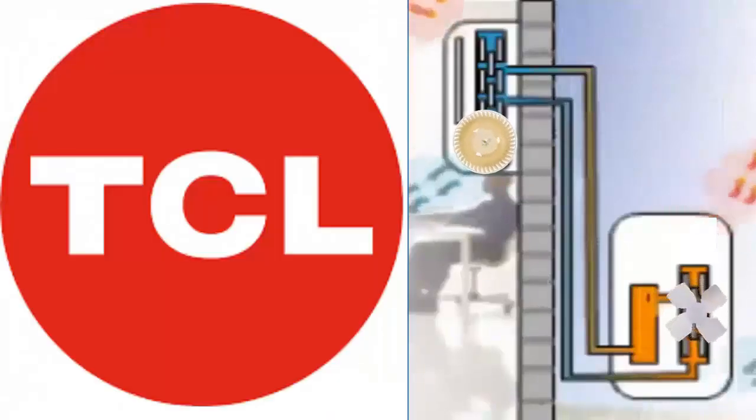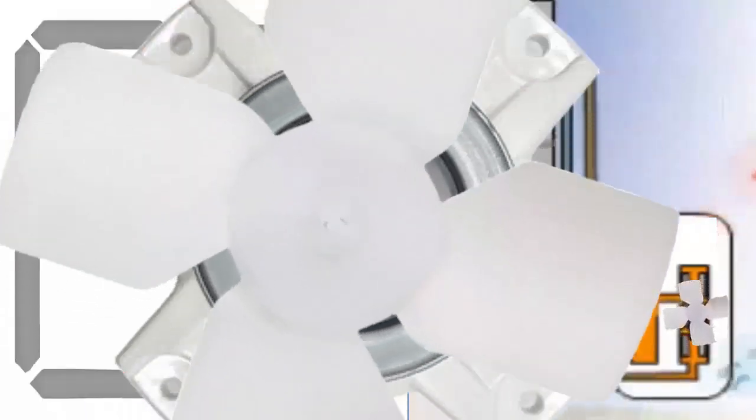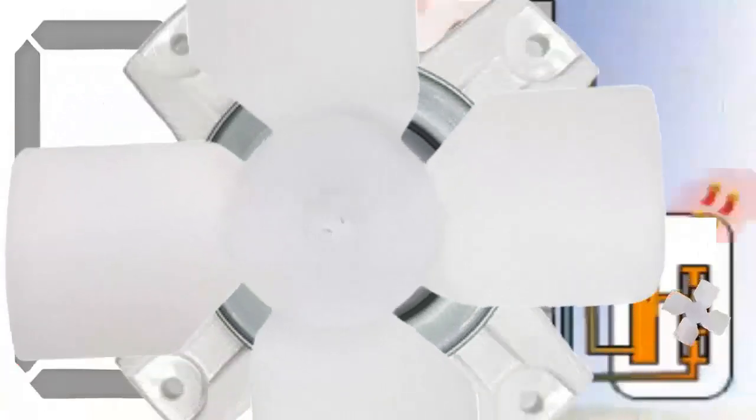4. Check the cleanliness of the fan and coil of the exterior unit to ensure the system is in optimal condition. Visually inspect the fan's rotation, and with the unit turned off, ensure that the fan blades spin freely to rule out any mechanical issues.